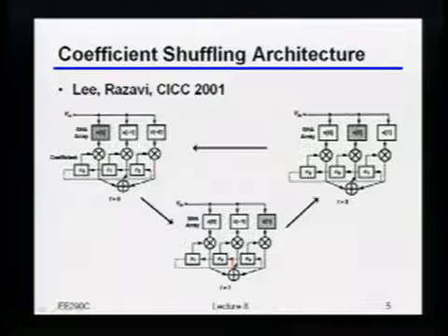Then in the next time phase, and the time phases here are obviously controlled by the clocks, and I'll draw a picture of that in a second just to make sure it's clear, I can still take that same sample that I had from one time phase ago, but now since I've advanced by one time phase, its meaning has shifted, right? So if before it was the cursor, then now it would actually be the first post cursor, right? Because I'm one time sample later. So I could just take that same sample value, and on this one it used to be x0, now instead of feeding it to c0, I feed it to c1, right? Because now it's supposed to be the first post cursor.